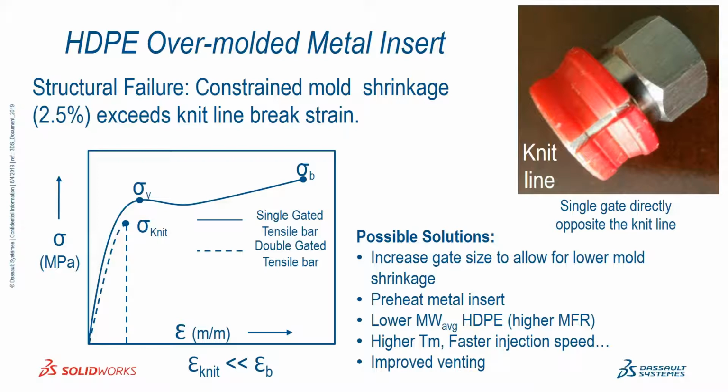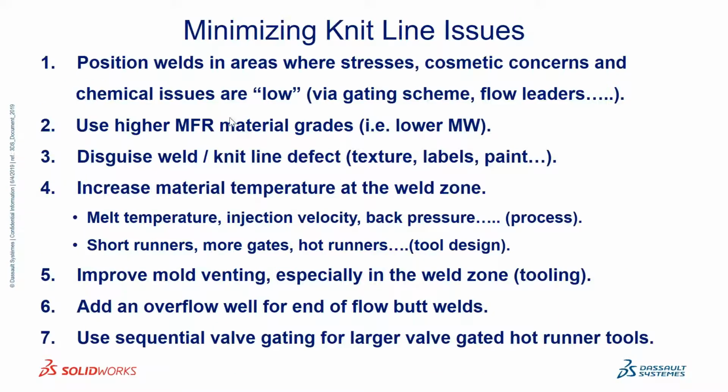Again, mobility of the molecules, fast fill, high melt temperatures, and in this case, preheating the metal insert would probably help a lot as well, because you're really losing a lot of heat to the insert itself, because the insert is made from a conductive metal. So that's a whole different situation, but also very common.